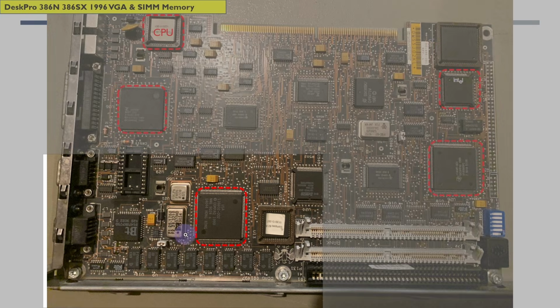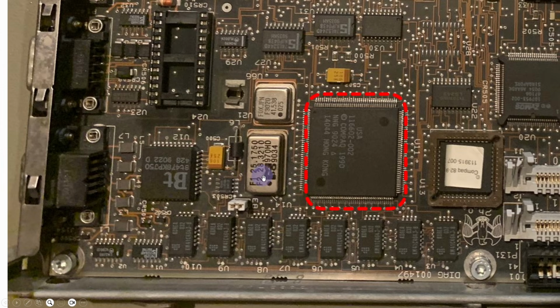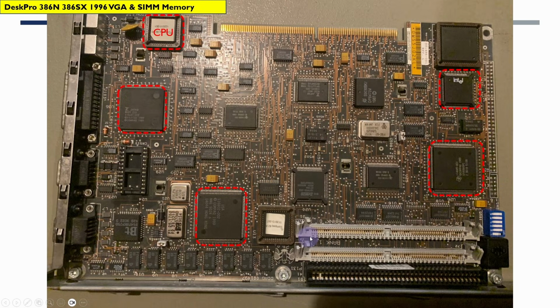If we go in here, you'll see down here we've got 25.175 megahertz and 28.3 megahertz. So these are the VGA frequencies needed for the 720 dot text mode and for the 640 by 480 graphics modes. And you can see here that the memory has now been replaced by DIMMs or SIMMs, and there is still, I think, the slot there to plug in the old memory cards and things, but things have moved on.